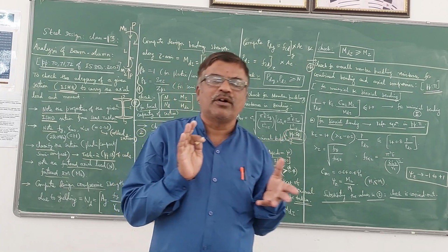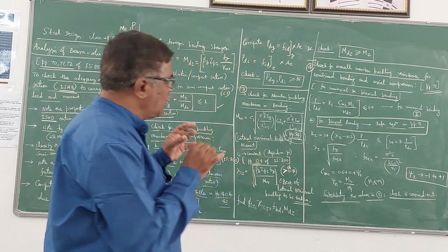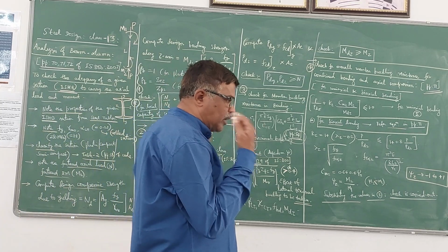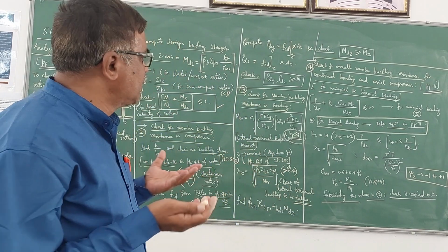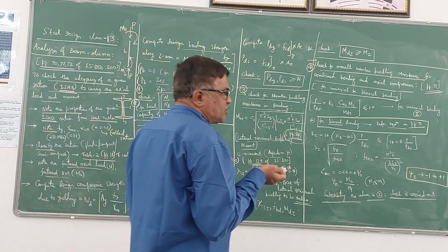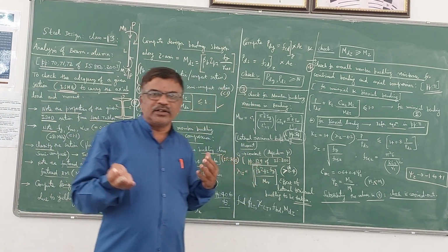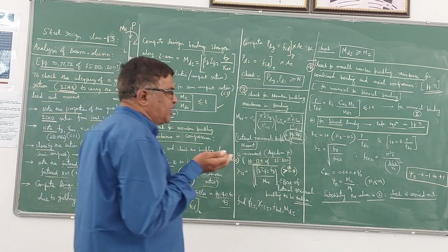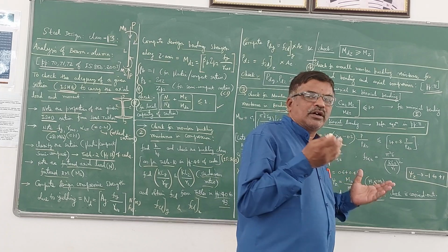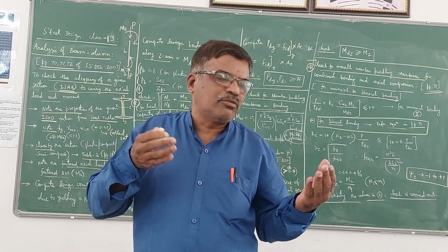This is in the case of axial load with uniaxial bending, with one moment predominant. If both the moments are predominant, My and Mz, in the case of biaxial bending, in the case of space frames, of course, you will come across both the values of My and Mz.